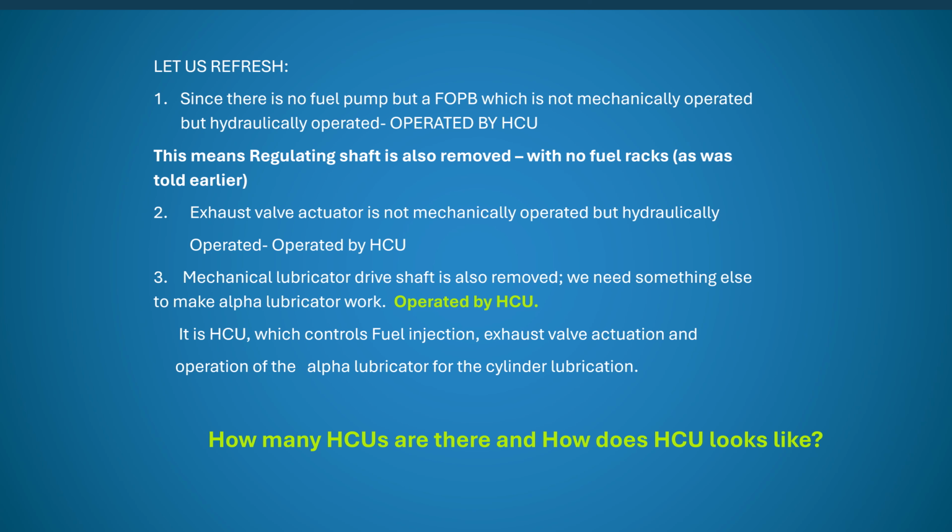So let us see what we have discussed so far. Since there is no fuel pump, but a fuel pressure booster, which is not mechanically operated but hydraulically operated by the SCU, the regulation shaft is also removed, with no fuel racks, etc. There was no fuel rack, nothing to move. So the electromechanical governor, as we know it, is not there.